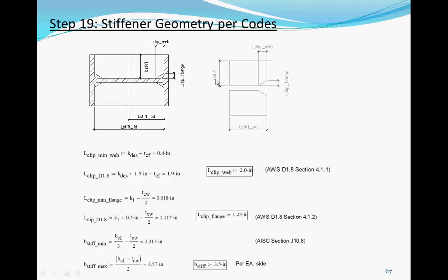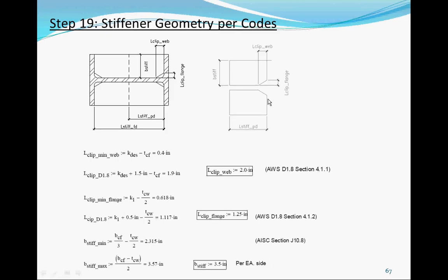So if I cut it out, that's what the stiffeners look like. In order to fit it within what they call the K area, this region, you have to clip out the stiffener corner so you could fit it into that. Once you cut it out, all you have is this area. Okay, so that's the area that's attached to that.